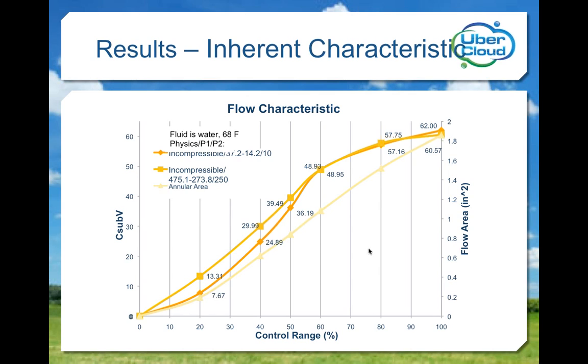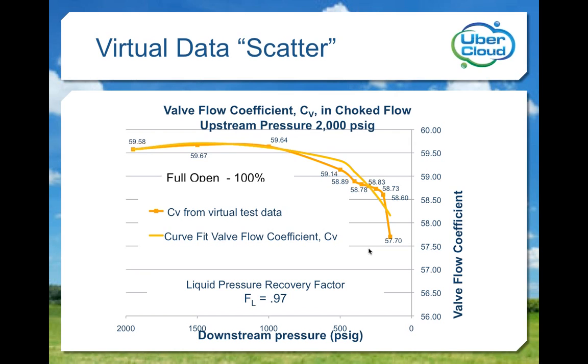All the data that was returned from the cloud looked good, almost eerily good, since I've seen physical test data exhibit similar patterns, and was exactly what I expected to see from a true simulation. One thing that was missing was a real-world phenomenon called data scatter, until I looked closer. As I've seen many times with physical testing, data in the choke flow region is not very stable. Why? Simply due to the randomness and chaos of the phase changes going on in the valve body. Instrumentation has difficulty in settling down.